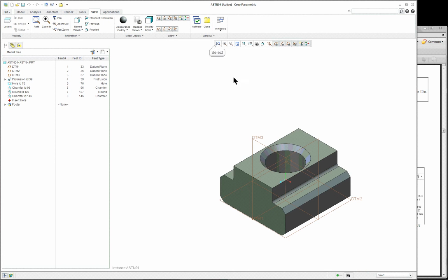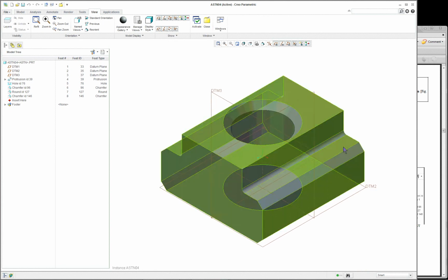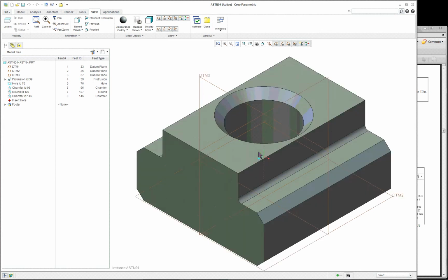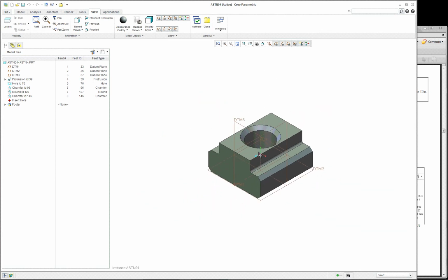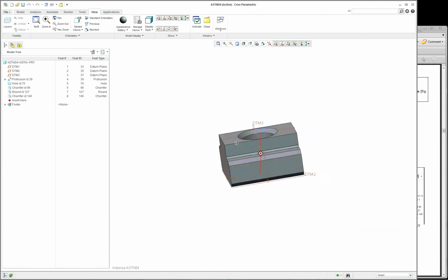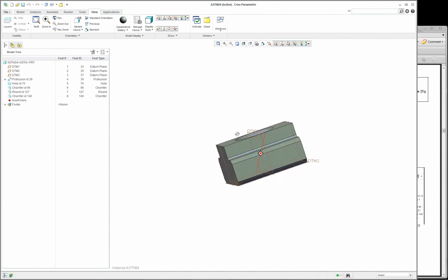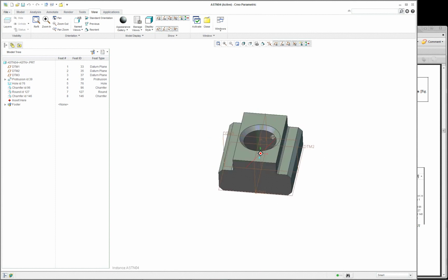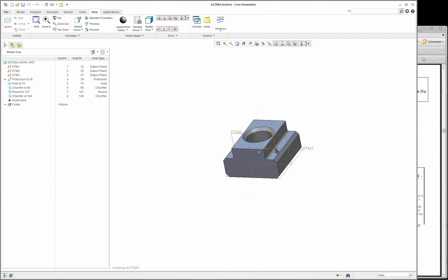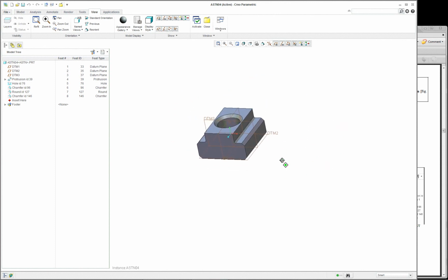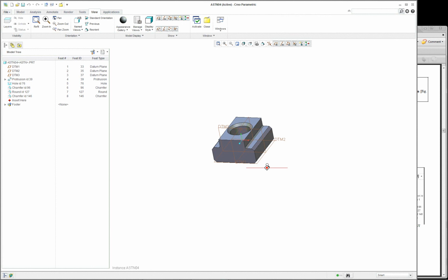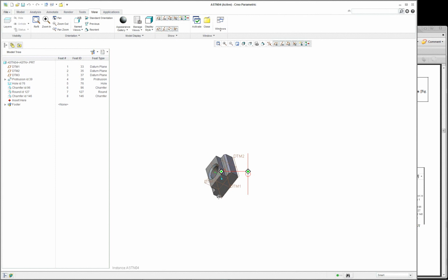Normally these commands, though, they're kind of old. Basically, you've got your 3-button mouse with a roller ball on it. So if you roll, it'll zoom. If you hold down the middle mouse button and move your cursor, you can get rotate. And if you hold down your shift key and your middle mouse button, you get pan. And you hold down your control key with your middle mouse button and you get zoom. And you also can rotate it.